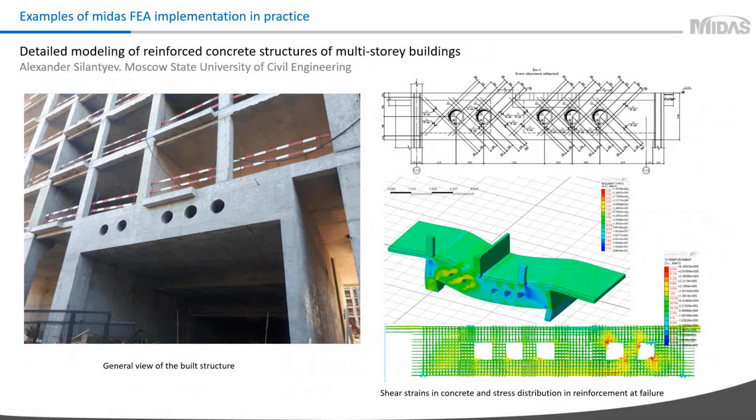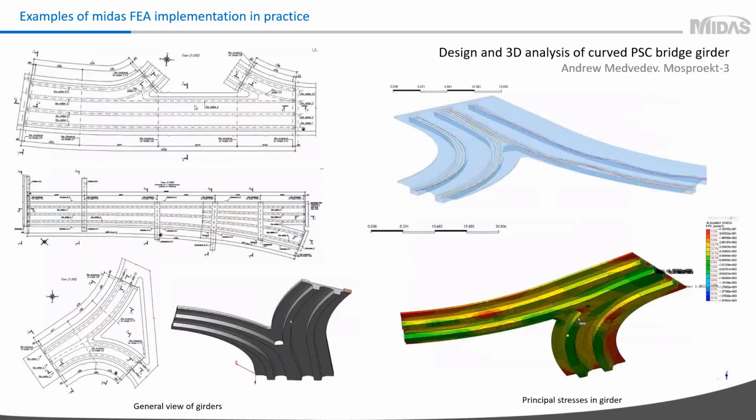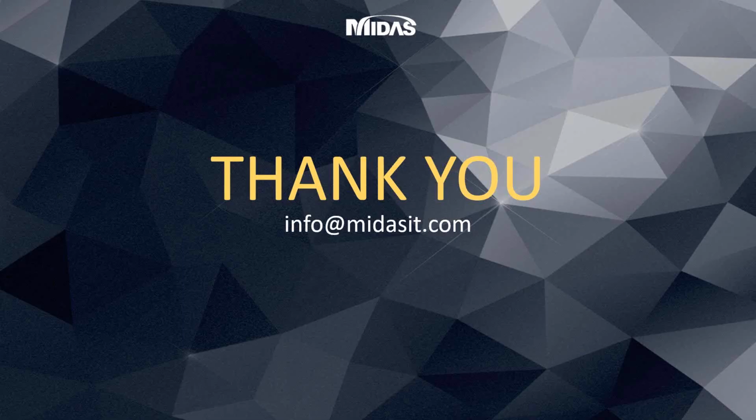And the last example is about design of a prestressed concrete bridge with complex shapes. Usually when an engineer performs finite element analysis of bridges, he works with quite simple beam models. But in this particular case, where there is a quite complex shape of girder, using beam theory is not enough for designing. Here the user created a 3D solid model of the bridge girder with embedded tendons inside. This allowed him in Midas FEA to consider the real behavior of bridges with different load actions.